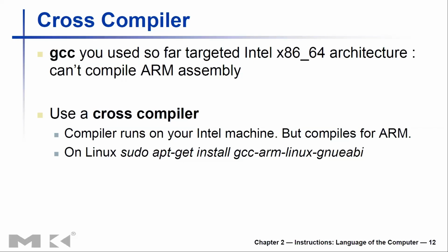But here we are looking at ARM assembly, so we need to get a binary that can run on an ARM processor. So the usual GCC you have in your computer, you cannot use it to compile ARM assembly programs. Here, with compilation, you will most probably be doing only the assembly operation, that is assembling.